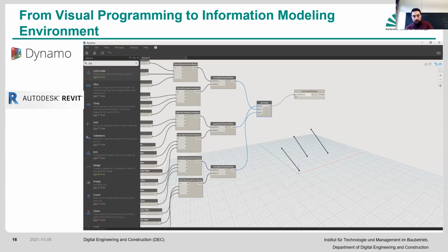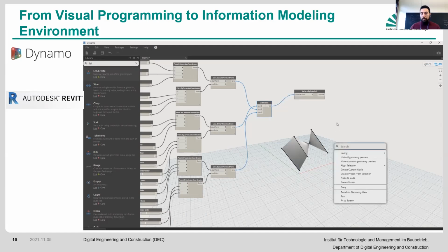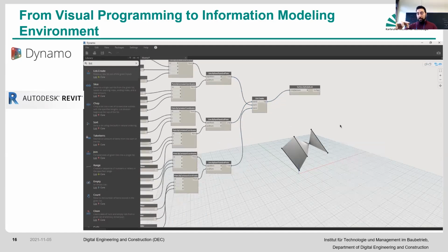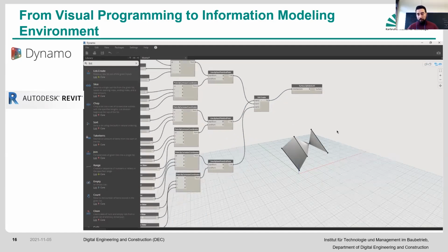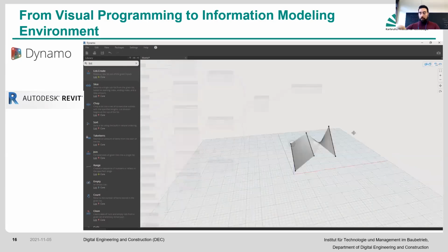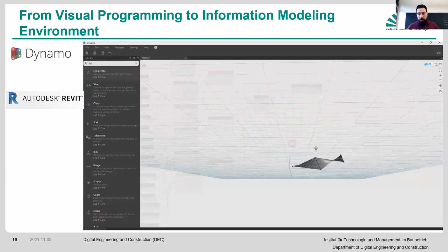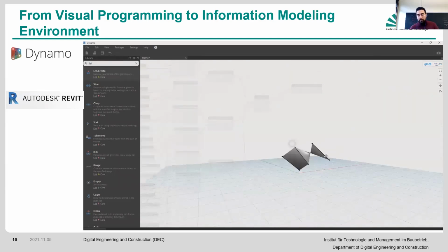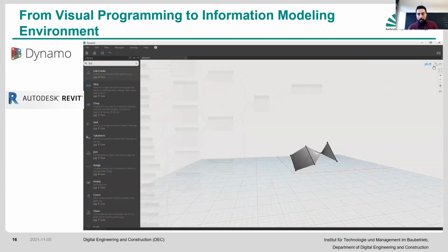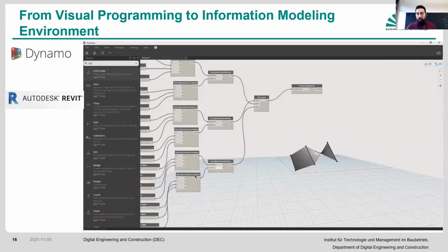And then you plug it in there, and it gives you a surface. Now, here at the very end of it, one of those two needs to be shifted, because it's starting to get one of these points to the other one. That's why it's kind of twisted that way. The only thing we need to do to fix that and loft it properly is to change the start and the finish of that line over there, which is the last one. So we go ahead and do that. We plug this to the start and the other one to the finish.